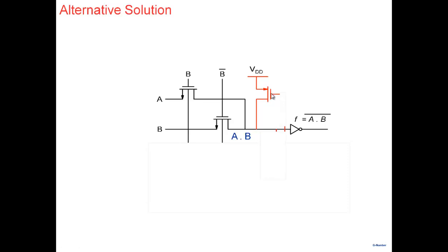So we are not adding PMOS to every gate. Note that it's not a transmission gate. We add a PMOS here, because PMOS is the one which gives me a strong 1, right? So we add a PMOS here. But then the goal of this PMOS is to take this weak 1 and make it stronger, connect it to this particular one. So now how do I do that?